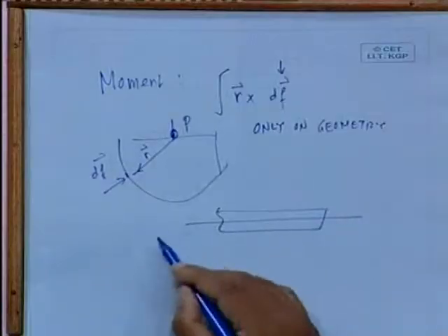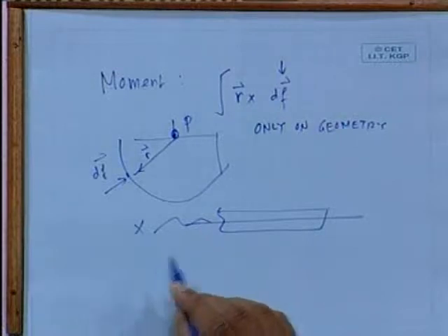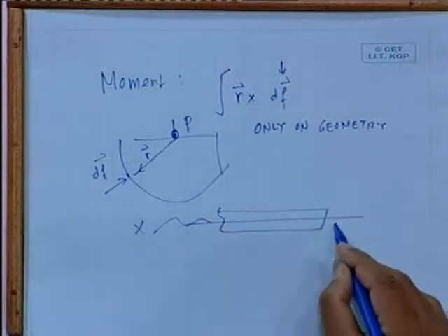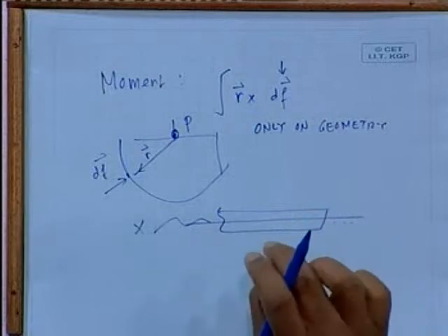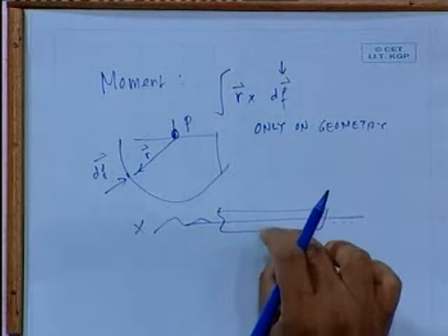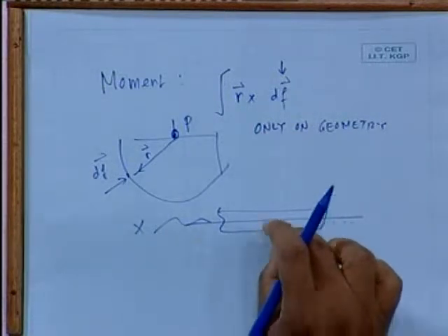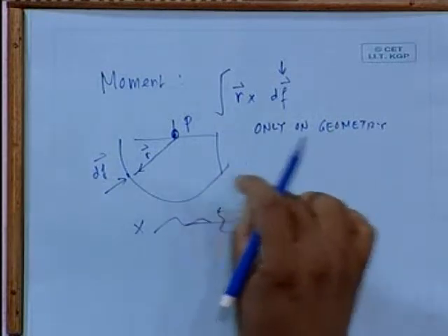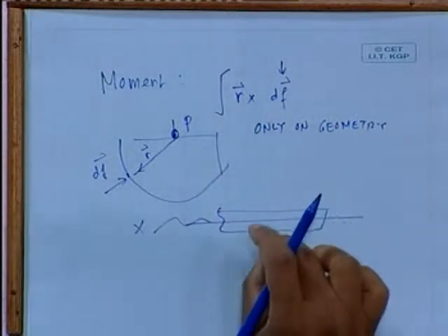because what we want to find out is that the ship is under water, and the water is always steady water. There are no waves, there is no gust of wind right now. As far as water is concerned, only steady water. So whatever force comes on the hull is only because of hydrostatic pressure, which is determined purely by the geometry. Okay. Now we only want to find out everything of the hull under that condition, and that translates down to a number of integrations, a number of quantities purely on the geometry.